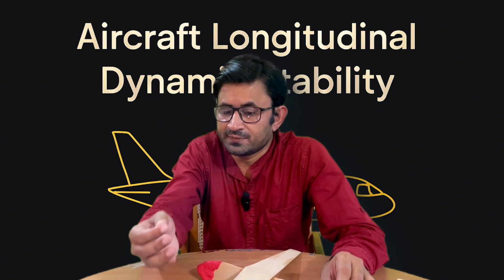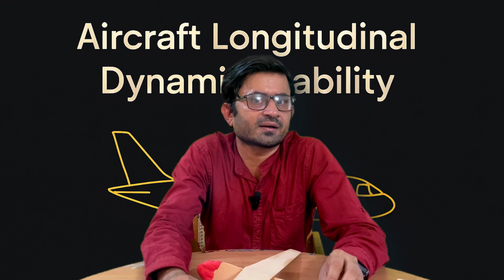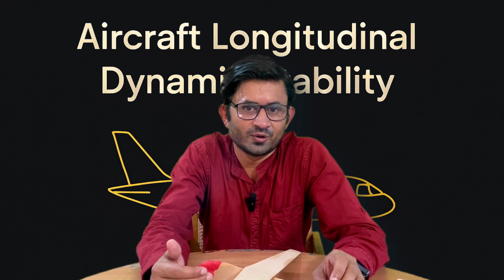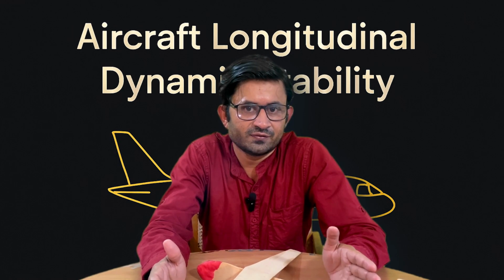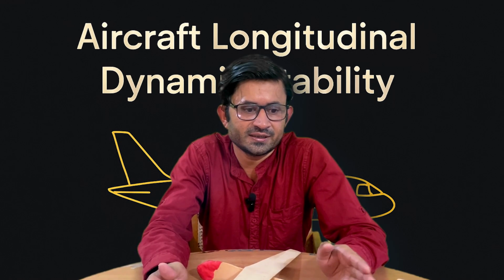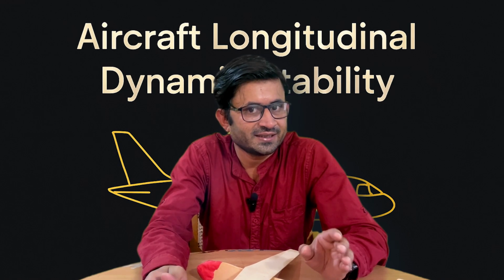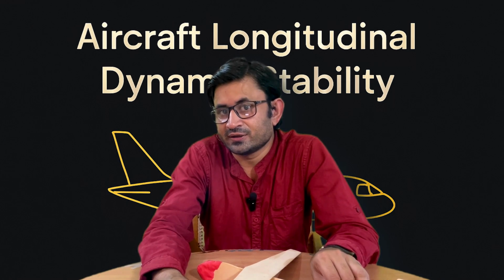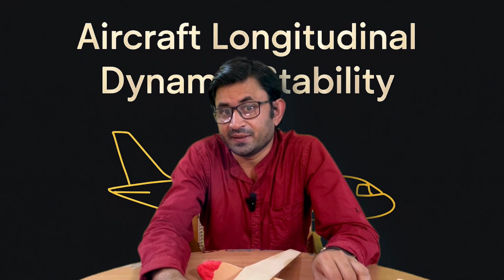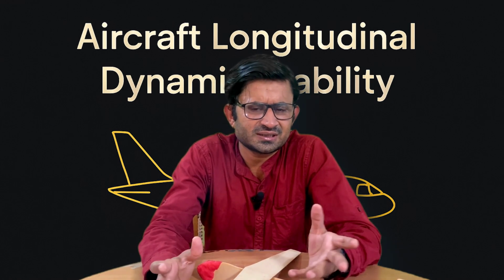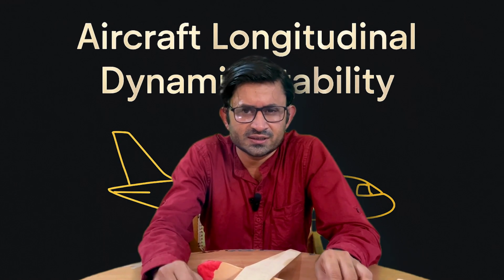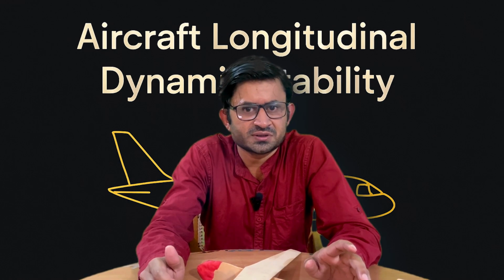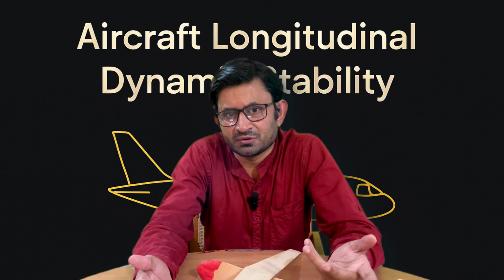You will observe that in this kind of aircraft you can easily achieve the long period mode, because zeta is inversely proportional to L by D. If you increase L by D, zeta will decrease. That is why in a glider case you can easily activate the Phugoid mode, but in the case of a fighter aircraft it will be difficult to activate the Phugoid mode. So this kind of feeling you can take. And when you consider the motor glider type, you will see the time to half its amplitude is long, for example more than 20 seconds, 30 seconds.